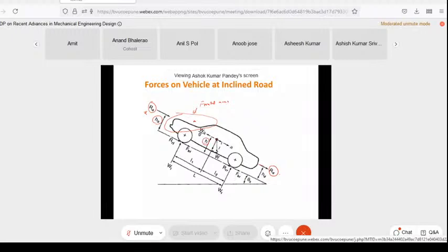And this is your acceleration, and this is your velocity which is acting, and because of the slope, it will push you downward like this, and along the body like this. Based on this component, that will decide how much your tractive force is, which is acting over here. These are called tractive forces, or braking force. If you are having braking condition, it is called braking force. If you have tractive condition, acceleration, it is called tractive force. These are the forces which we also call longitudinal force, that I was talking about, that develops in the tire. So these are the forces that you have to use.